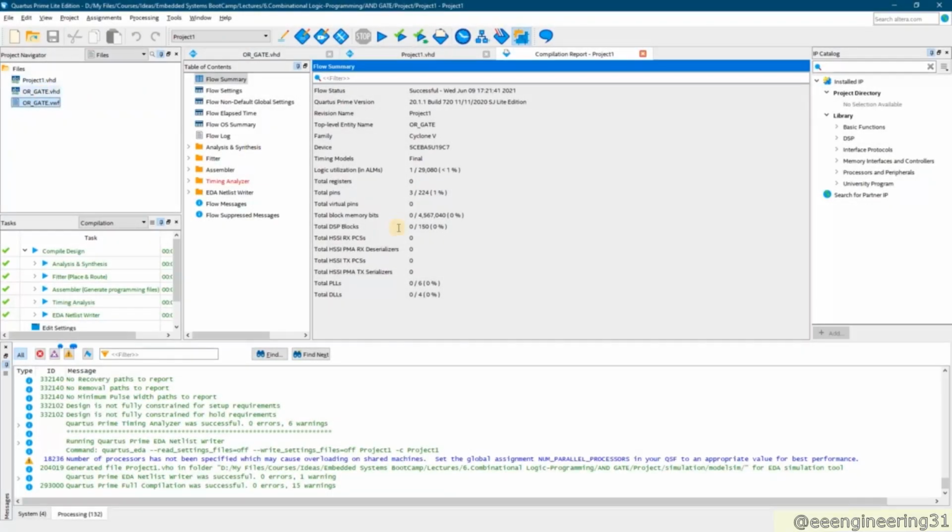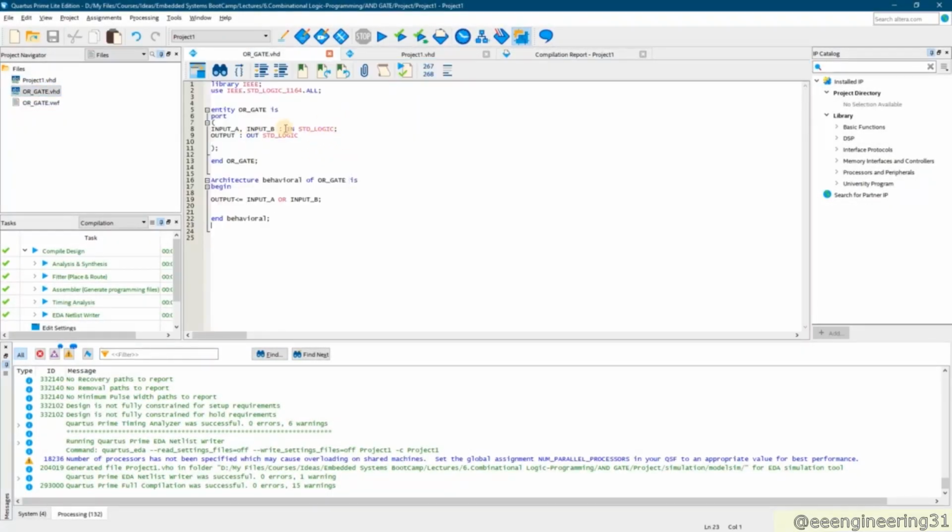So now let us continue here. So what if I have more inputs than that? Well, that's very simple. Let's say I want to create an XOR gate with 3 inputs. So I just need to add input C. And I need to add here, instead of OR, XOR. And I need to XOR the other input. So I have all of these XORs. And this is input C. And I need to call this XOR gate in these 3 places.